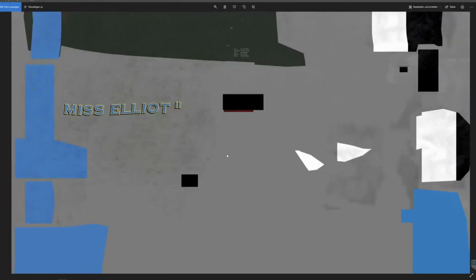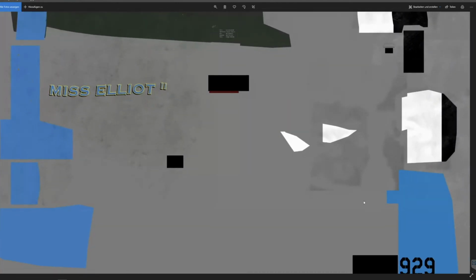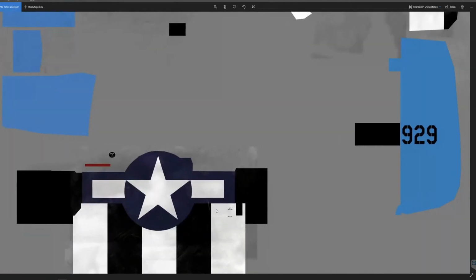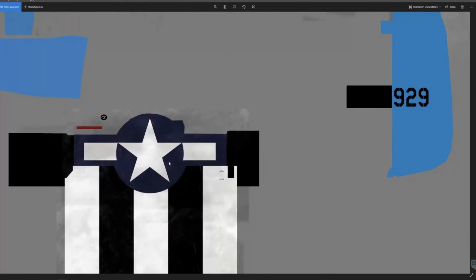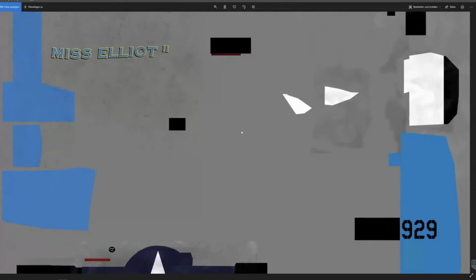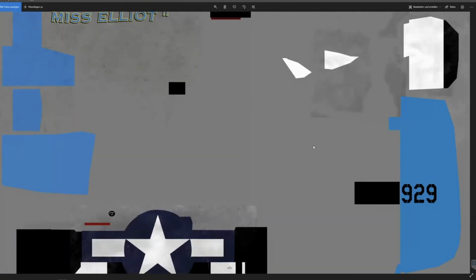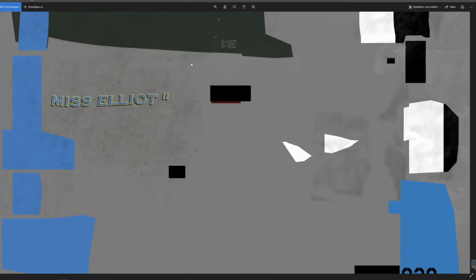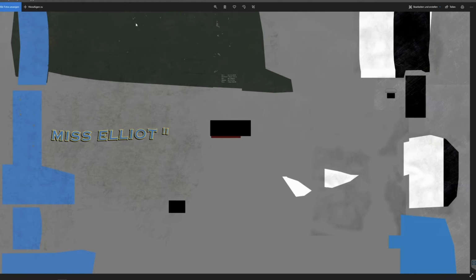So a few parts of the plane are just painted material, and this texture is also mixed with some procedural textures, so that simple color texture basically works. And as I said, most of this is pretty much empty because there's metal on the plane anyway. So this shader that is using that texture is only ever being applied to parts of the plane that have this paint material.